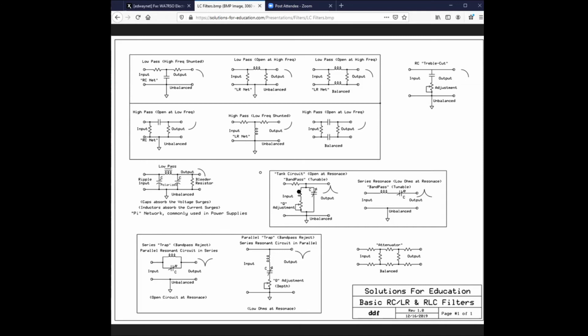Now, a coil is going to be a coil of wire or a conductive element, but it still will have a certain amount of resistance. And when you get up into RF, this coil might be a small tube. And in fact, if it's high enough frequency, and if you really want quality, it's a hollow tube, but it has silver plating on it. That's because of what's called skin effect, if we have time to get into that. So as you introduce more resistance, you change the Q, and that will affect the bandwidth. In that same respect, you could adjust that here in this one, because this resistance is here. As you add more resistance in, you're lowering your Q. And the Q factor will have a deliberate effect on the bandwidth, or what you could call the pass band.